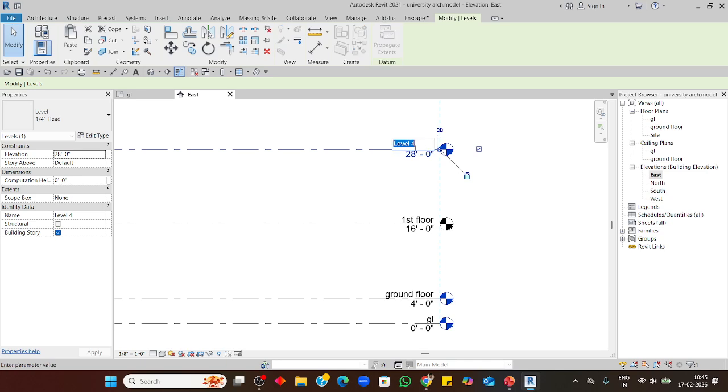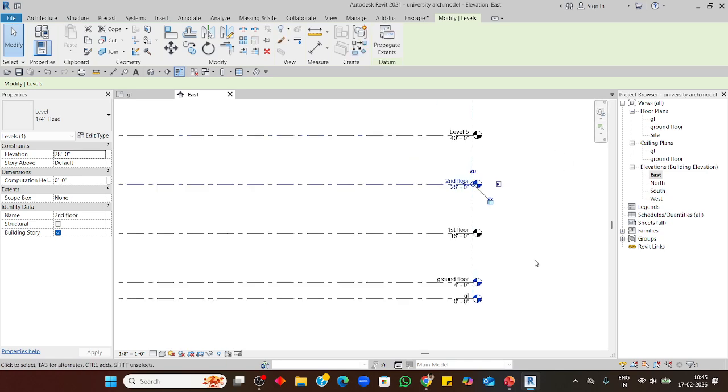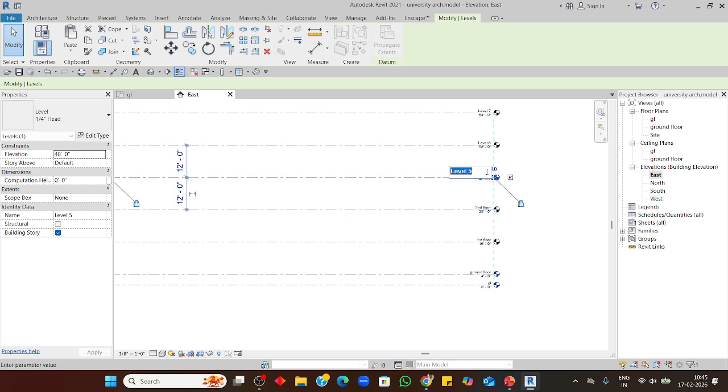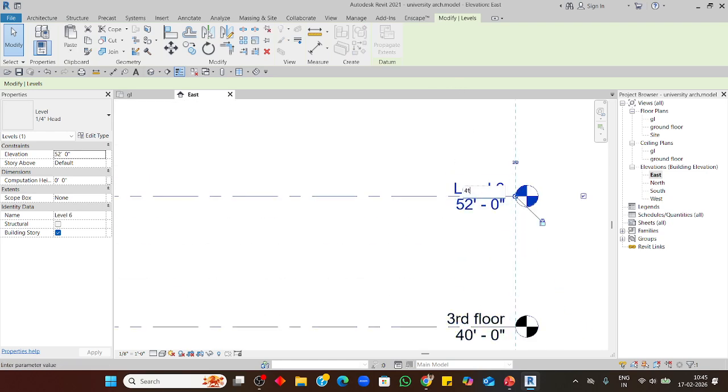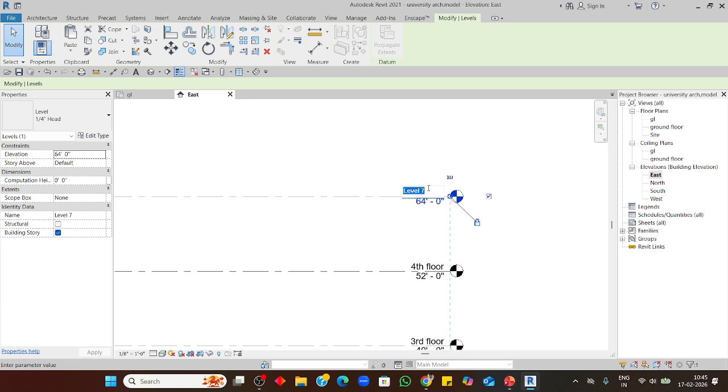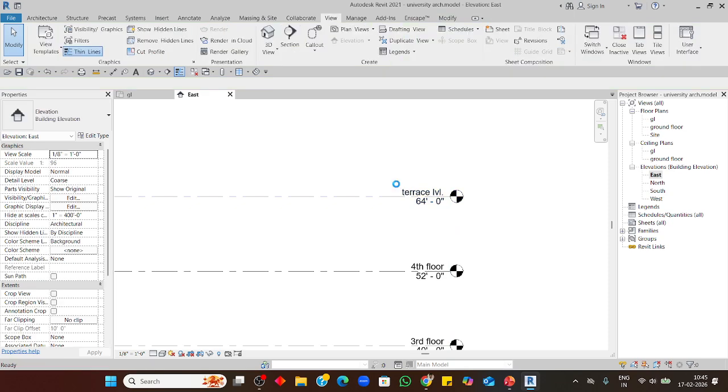And we have to rename the floor plan, ceiling plan, structural plan, if any. Now if you press enter, nothing will come. First, we have to create the levels. Now go to plan views, floor plan.